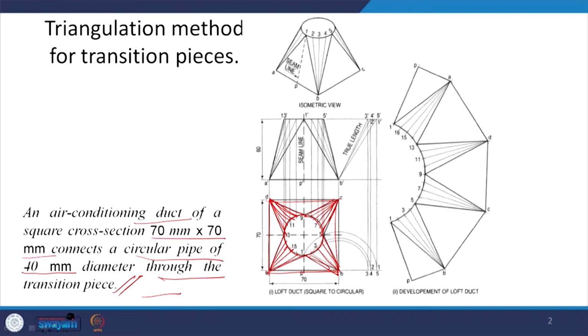So, what we do here is we will start by drawing. Depending upon where the stitching is going to happen, where the sheet is going to be put together, they have assumed that here is the seam line where the sheets are going to be stitched. So, if we look at this, we will have the half of this triangle. Now, for this, we have to look at the actual slant height of this, which is what we are going to get in the elevation.